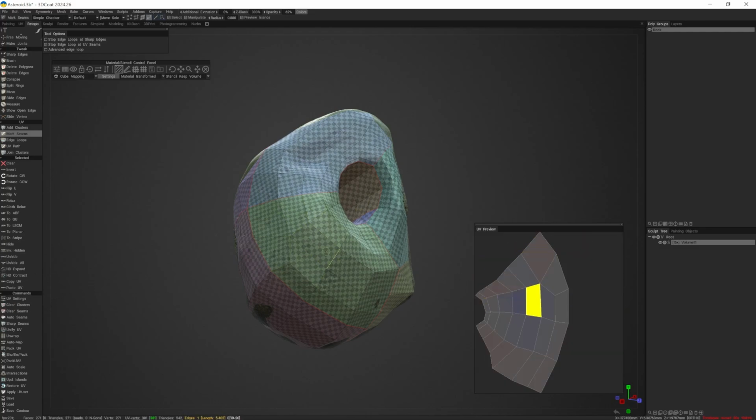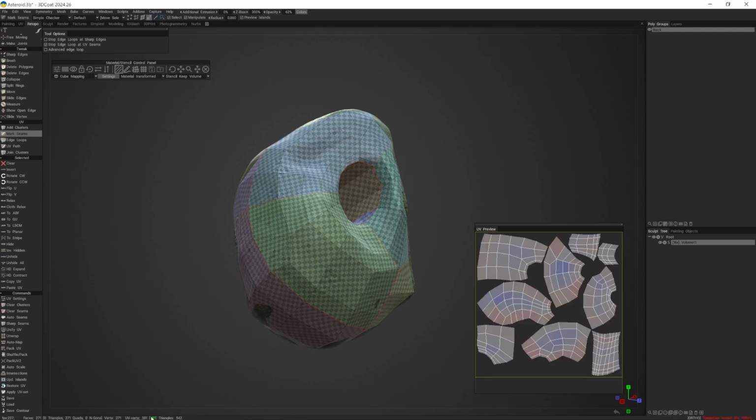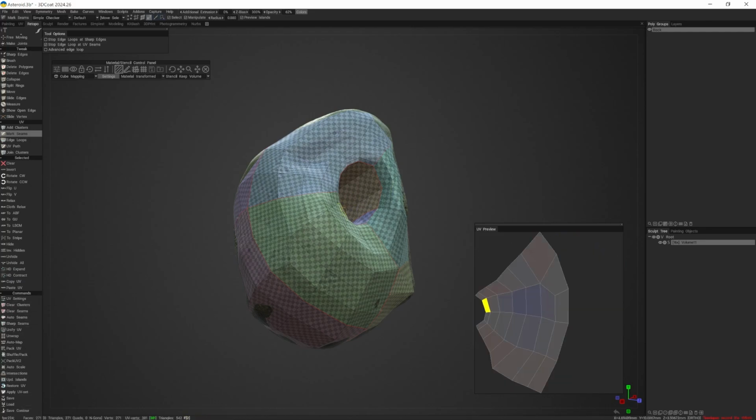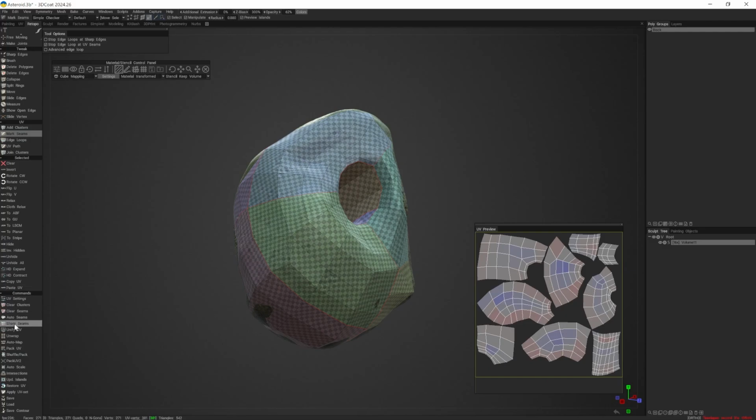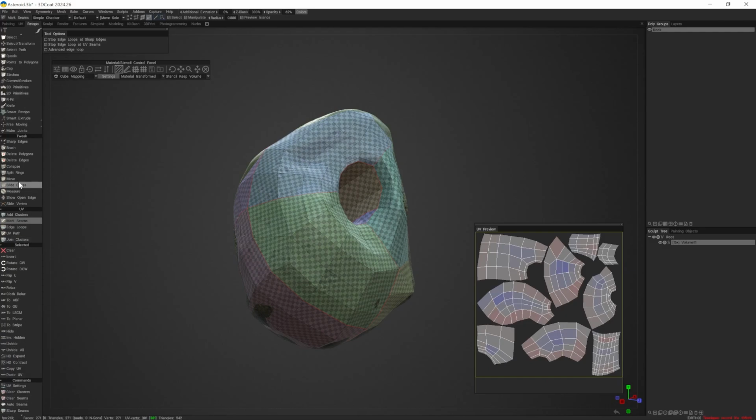Anyways, we have all this, and the one last thing I probably want to do is increase the poly count. So I think this is how many faces? 271. You compare that to 5 million, it's pretty good. But I'll go ahead and subdivide this. Let me subdivide.